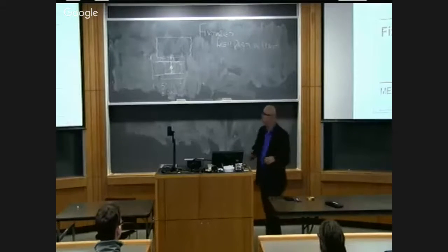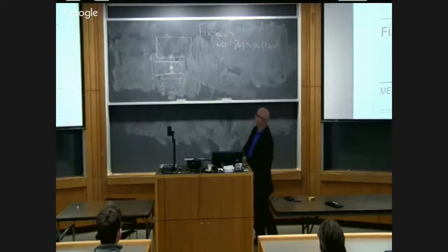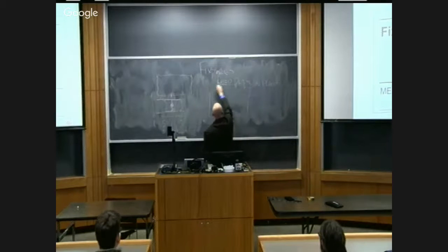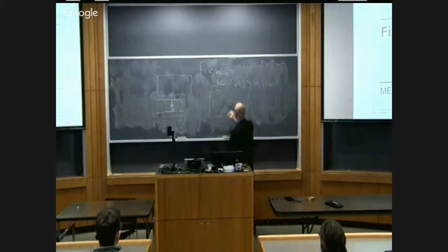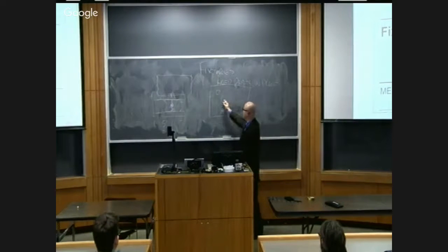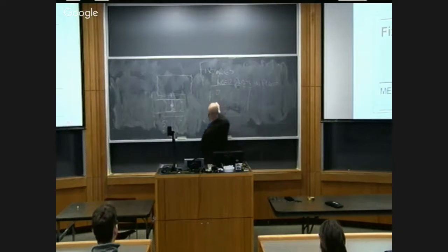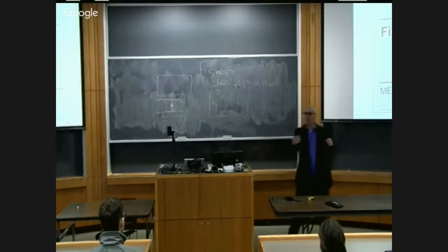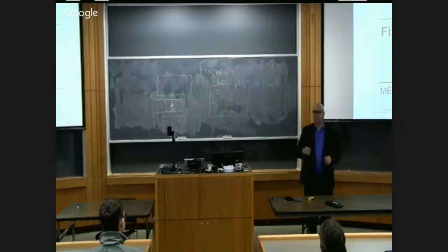So our mini mill has a work envelope, right? So we've got the table, and we've got the probe over here, and the way we commonly have them set up, there's a vise here, right? And there's a column fixture here. But these things are both attached to the table, and they can move. Frequently, if we have a big part to cut in the vise, we'll slide this over. It's completely out of the machine, but it's okay to slide it over. So we'll loosen the bolts, slide it over. Don't forget this step, tighten the bolts again.